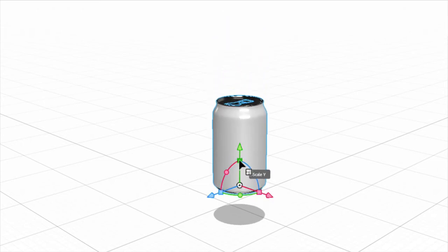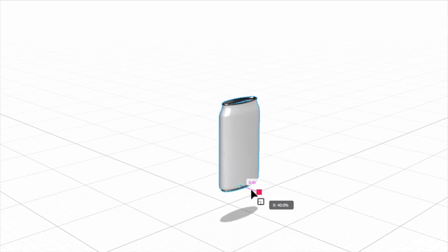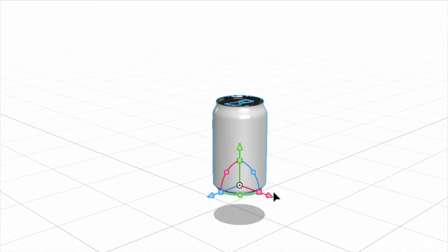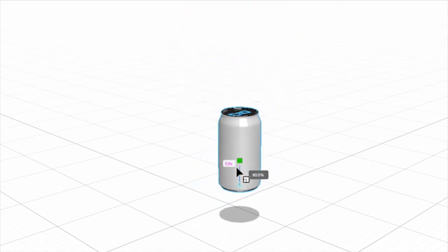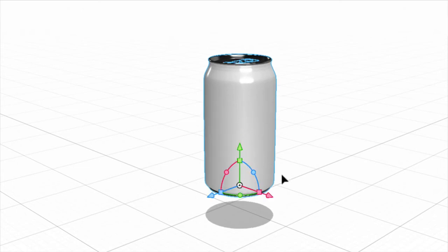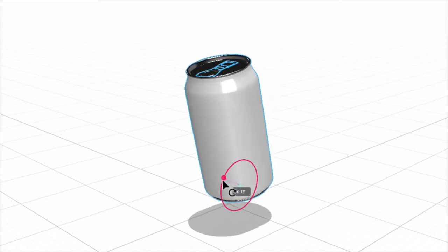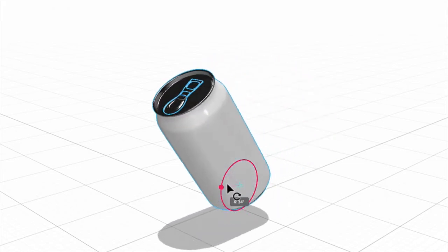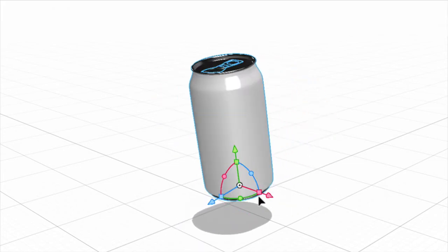Now, of course, if I click on just one square, it's going to move it in that one direction or that one dimension. I can always do Command Z to undo. Or if I hold down Shift, it'll do it in all 3 dimensions. So this is a great way of scaling it up, but keeping everything proportional. Finally, if I click on the little circle, this will allow me to rotate objects in that plane as well.